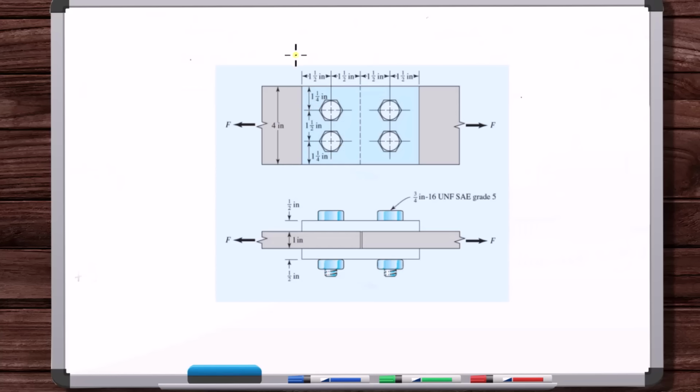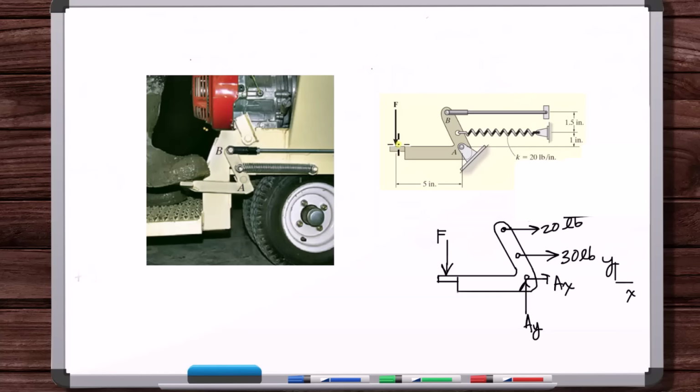So this bolted plate is not designed to have any loads in this direction. If there were loads coming from those directions, they would have a different design here. So we're looking at it from the standpoint of, for this direction of load, is this connection of two plates here, as a unit, a rigid body? When you apply a force in that direction, does the geometry change in that direction? Right? So you think about the idea of rigid body on a direction by direction basis. But even more than that, so here, well, no, it's not a rigid body.